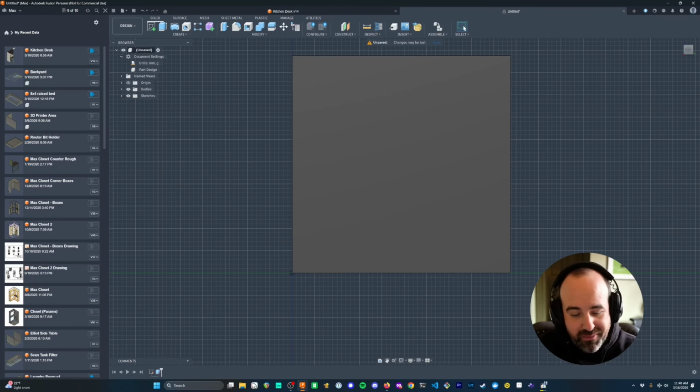But if you think about a box, it's just 4 sides. So I usually like to do it where the bottom and the top are kind of inside the sides if it's going to be fixed in place, because there's less edge banding you need to think about. You're not going to have these 2 edge pieces sticking out on the sides that you have to deal with.